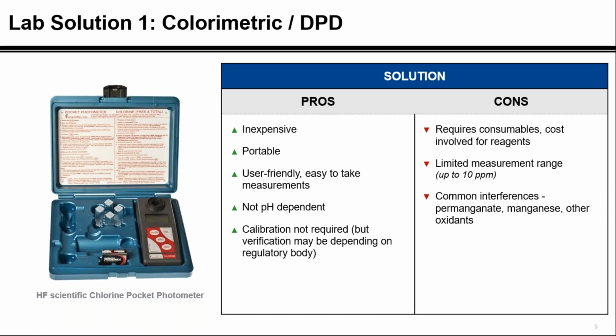And so if you have staining on your sample cell or scratches on your sample cell that made the sample look darker, those were not identified in the comparison basis. And so there was a lot of reading error and a lot of controversy over actually doing that with the human eye. The new methods using light and measuring absorbance, as well as zeroing on the same cell in which you react the sample, removes the human error from the equation.